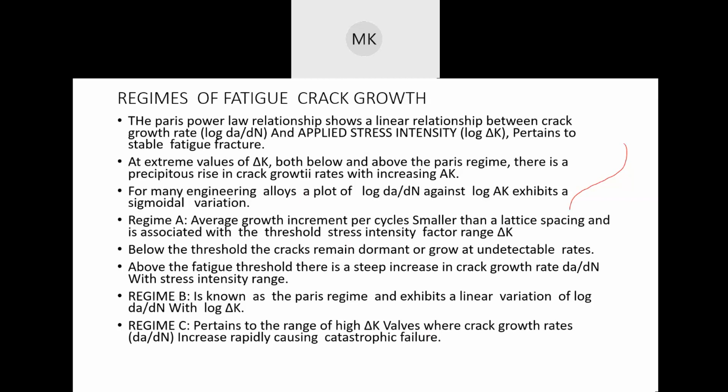So that's the reason why, when they start looking at failure and fracture surfaces, they want to figure out the point at which they have to replace the part. Just because you see a small crack in the sample doesn't mean that you have to replace the part immediately, but you have to understand the size of the crack really well, and see whether the crack size is still way below the critical crack length. And once it is even closer to the critical crack length, that's when you have to replace the part. If you don't, it can turn from "good, it's still working" to "oh no, it failed pretty quick," and you would not know how fast that is going to happen.